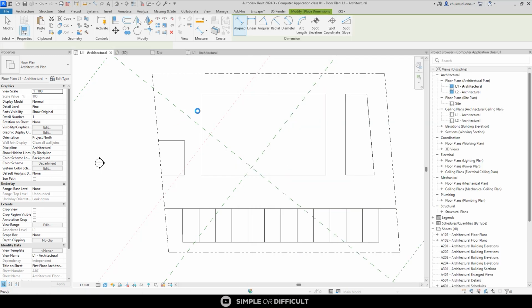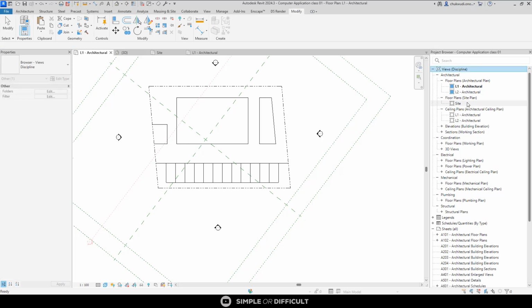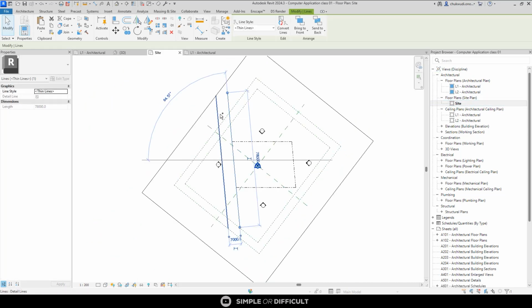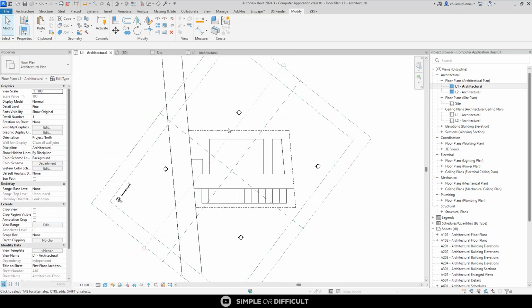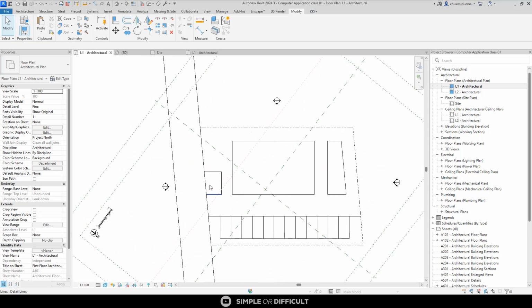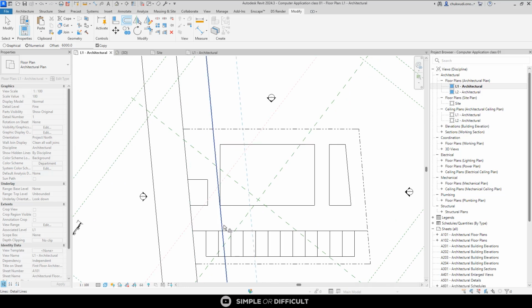Now back to what I was saying before, okay? I want to show you, when you go around this building, let me even go and bring the road. I'm going to copy it, Control C, and then I'm going to come over here and drop it here. Okay, as you can see, that's the road. So from the road, we're supposed to have like 6 meters to the building. And when you do that, you find out that we're having 6 meters, because I want this building to be straight, not following the side boundary. You can see we're having 6 meters.